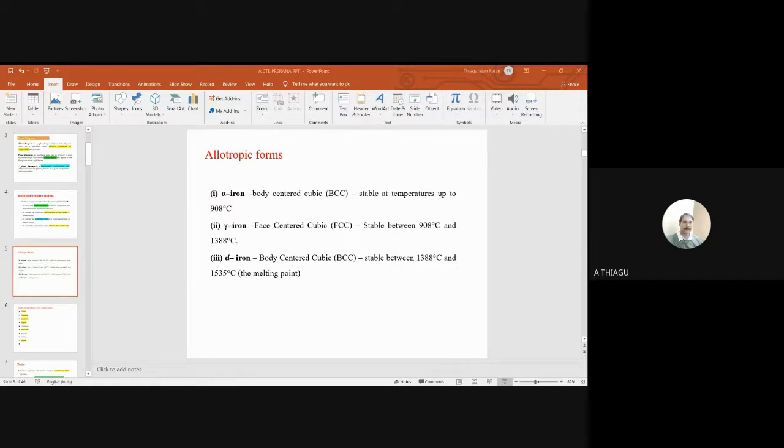It has many flakes of carbon in a matrix consisting of ferrite, pearlite, or a mixture of the two. In most cases, ferrite (alpha) and pearlite appear. The advantage of gray cast iron is its very high damping capacity, in the sense that it is a vibration resistant material. It also has good dry bearing qualities due to the presence of graphite. So one important advantage of gray is its high vibration damping capability. In the next slide I will show an example and you can easily catch up.